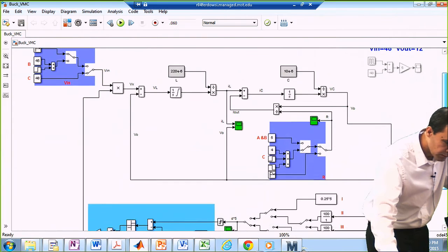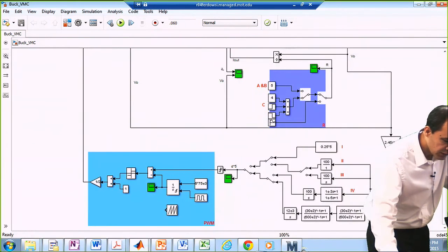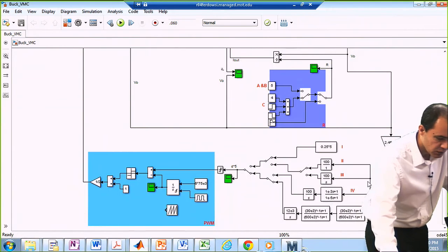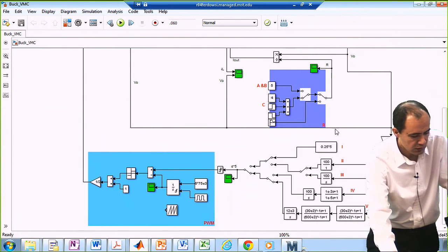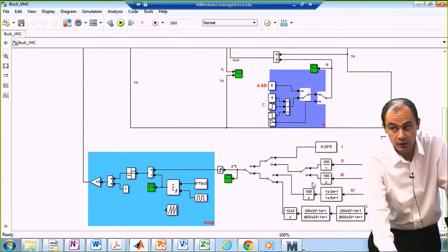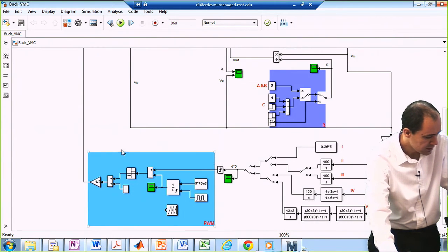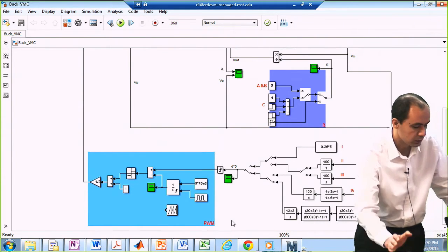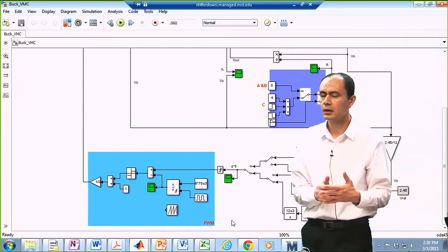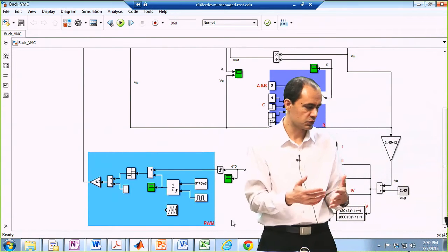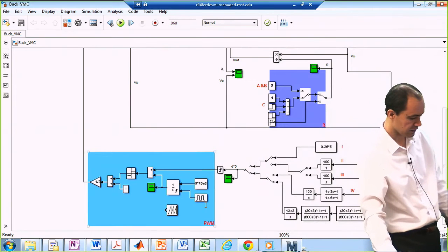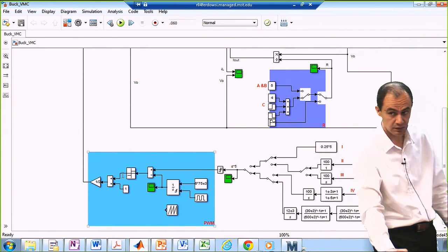Okay. And then down here, I have a bunch of suggestions as my compensation network. So this is implementing my G of C, my compensation transfer function. And this down over here is my PWM block. So I try to make it as close as possible. If you purchase a chip, basically they have a constant current. They integrate that constant current. Then they reset that capacitor, and then compare it with the duty cycle signal, and then the rest is like your gate driver or something like that.